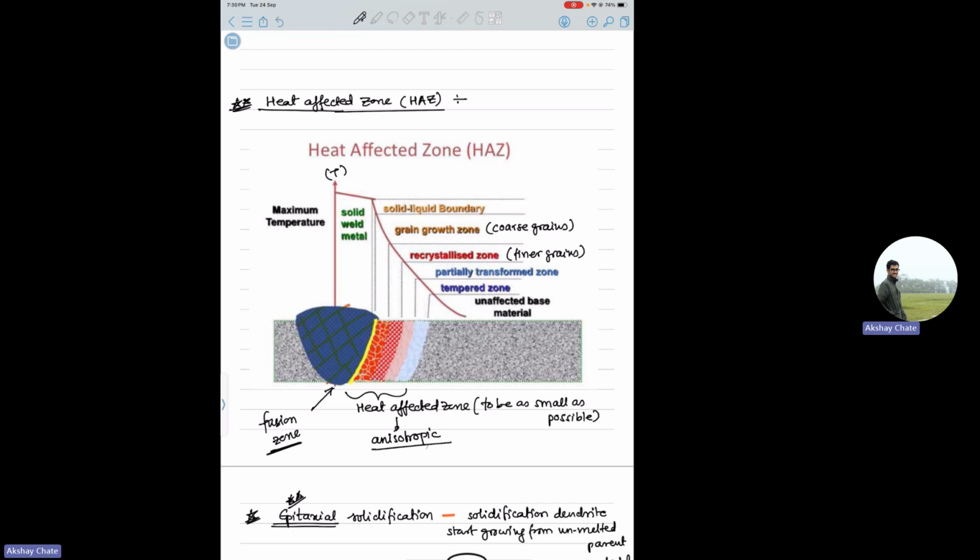That's why many times laser welding is preferred for critical applications such as satellites. In those cases, you don't do normal arc welding mostly because of these things. You usually prefer laser welding. Cost is more, but the sensitivity of the application is also important there.